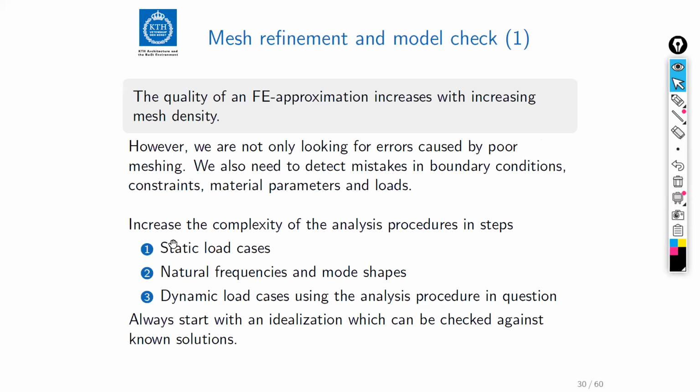Okay, so we would start with some static load case, maybe gravity load or something else that is related to the problem at hand. And with this static load case, we can compare with some simple tabulated values for different basic load cases, and just make sure that the orders of magnitude of everything are reasonable and correct. And when we're happy with that, we compute the natural frequencies and the mode shapes. We solve the eigenvalue problem.